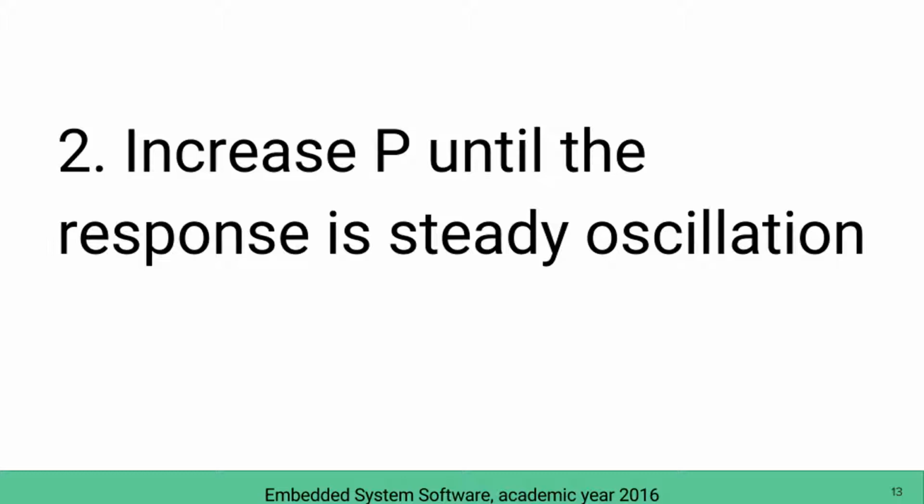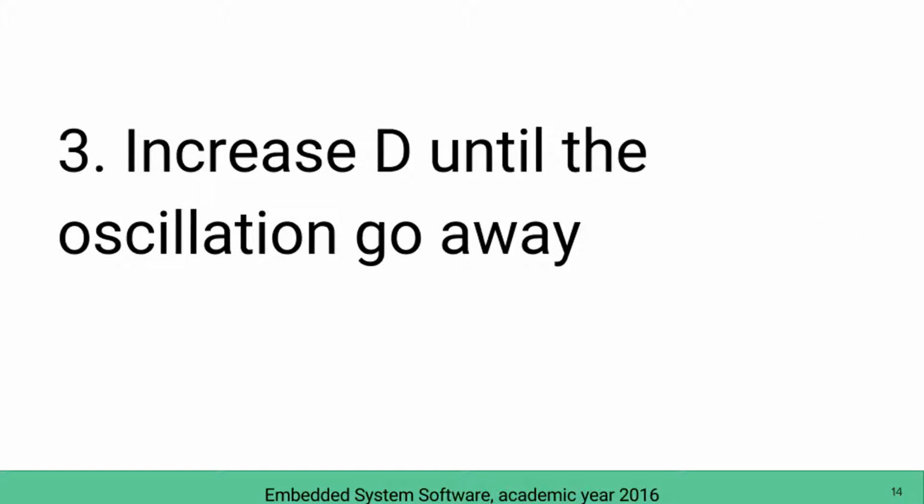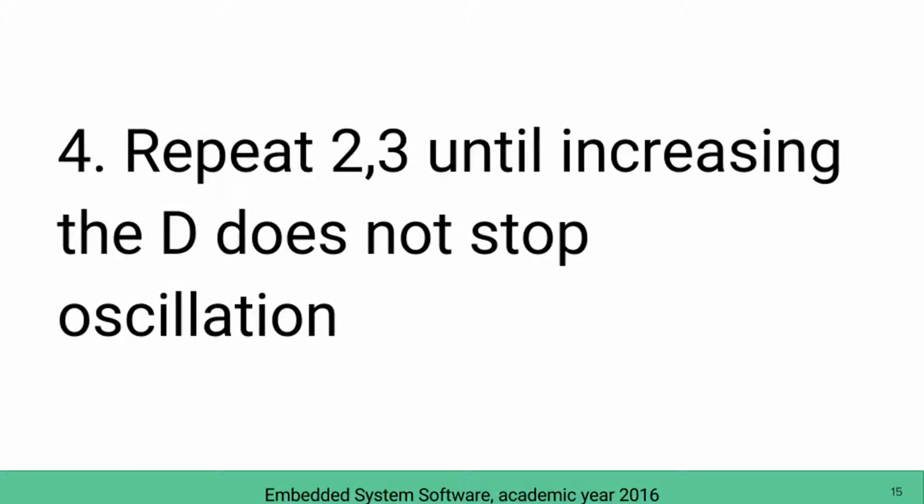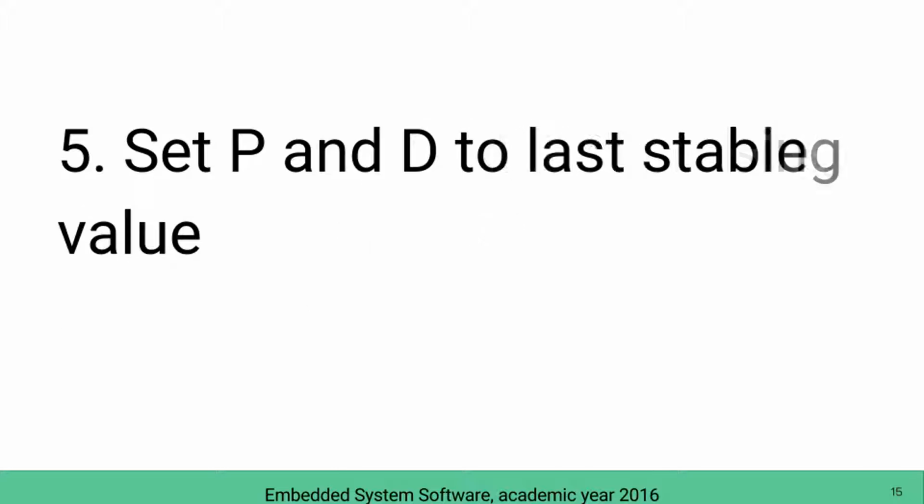Second, increase P until the response is steady oscillation. Third, increase D until the oscillation goes away. Fourth, repeat steps 2 and 3 until increasing D does not stop the oscillation. Finally, set P and D to the last stable value.